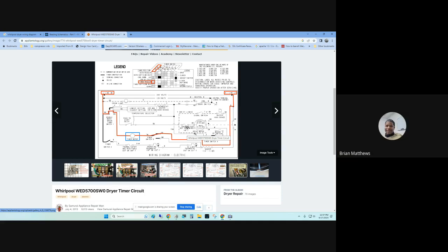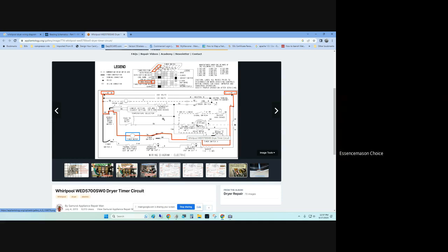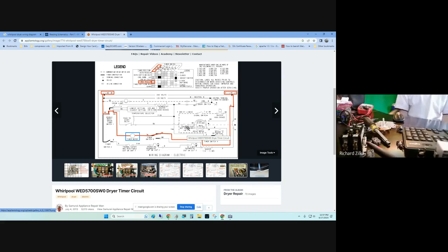You got to find out why it's actually making it blow. Exactly, because it's a fuse. If you put a fuse in a microwave that's got a blown fuse, sometimes you put a new fuse in there and it's working, but sometimes you put a fuse in there and it blows that fuse too. Changing the fuse doesn't always fix the problem. You have to find out what blew the fuse in the first place. So the operating thermostat, if it doesn't operate like it's supposed to, the thermal fuse will go bad and shut the whole dryer off. So, hey, we're getting too hot. We're going to shut this thing down and have someone come out and look at it.